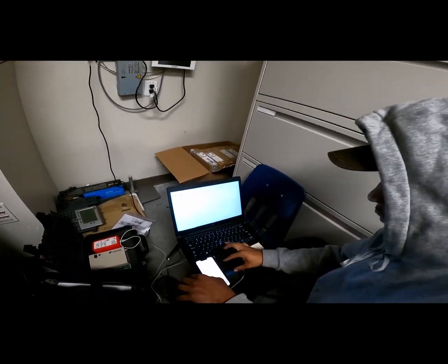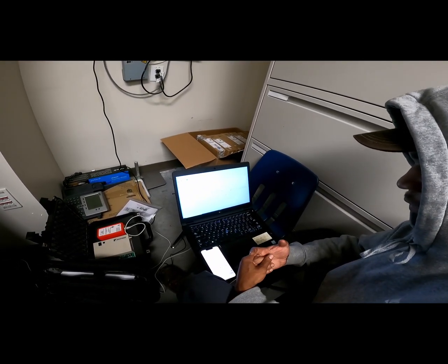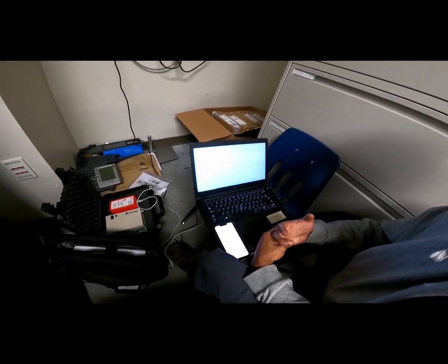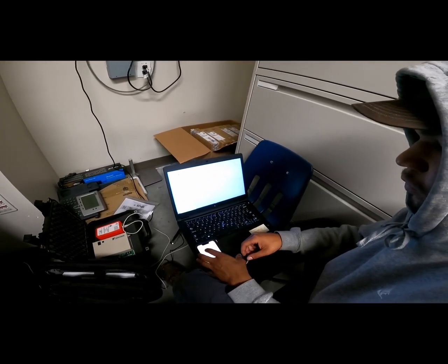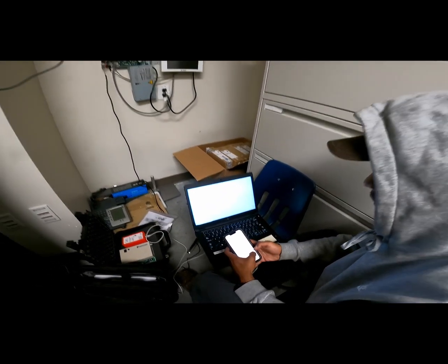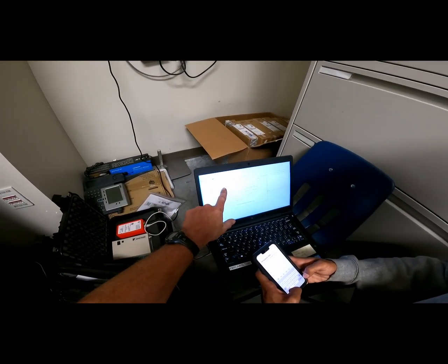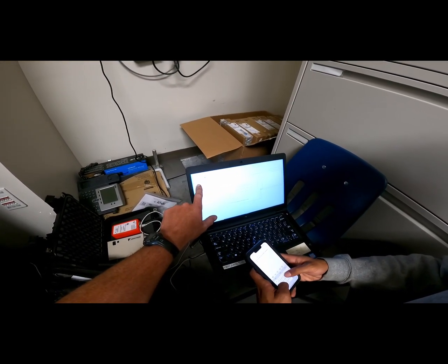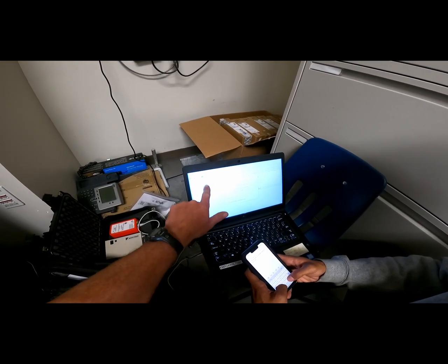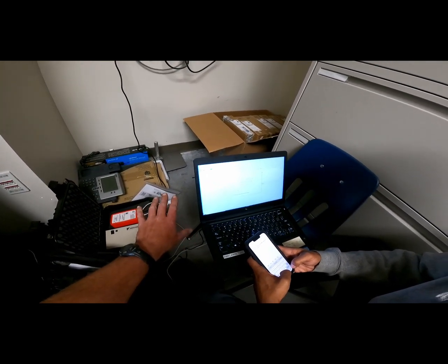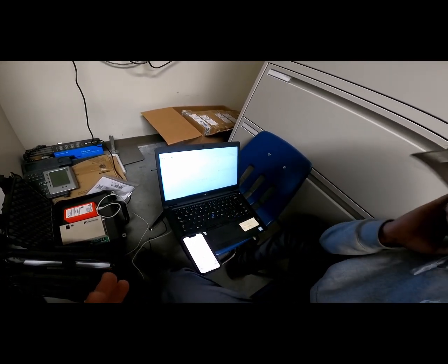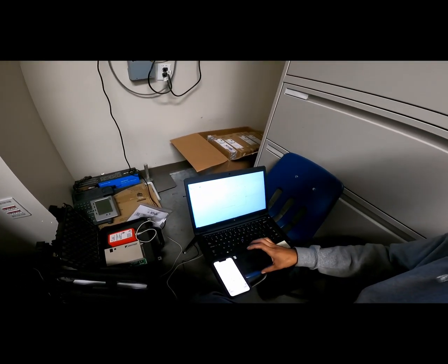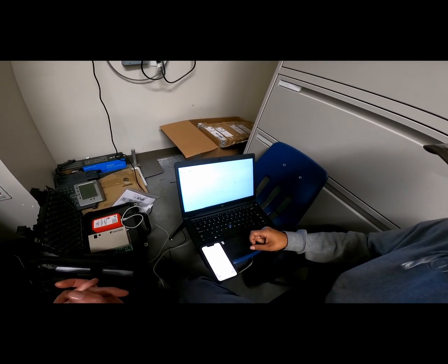Those are two different ways to find all of your units that are in the building that have an address. I've never used manual. I always just use auto. So go ahead and click auto. And what it's going to do is run through every possible address in the system from 0 all the way up to 253. This system has 4 different City Multi systems all on one network, all on one M-Net. And therefore it's going to take forever to search for the addresses.